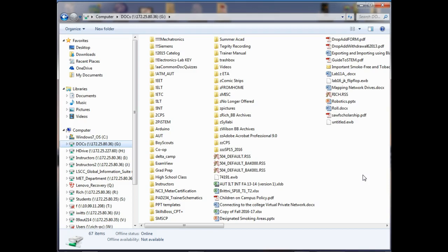Everybody okay? Now, what types of counters do we have available with RSLogix? Yeah, count up and count down. That's the only two that we have. We don't have a combination counter. There is another type you'll run into, the count up, count down, which has multiple inputs, a count up and a count down input. But all our timers and counters are single input. We use that single input as an enable, and as a count input or a time input. Does that make sense?